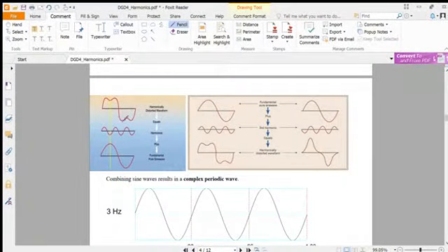So this is the harmonically distorted waveform. If we subtract it, then we'll get this, the third harmonic component, and this, the fundamental component. And this figure is the same because here this is the fundamental one, and if we add this third harmonic, it's a sine wave and this is a cosine wave, both are sinusoidal. So we'll get this wave shape. The shape of the wave can be derived by the Fourier transform. Later on we'll see how we could derive the wave shape here. So both curves are harmonically distorted waveforms.